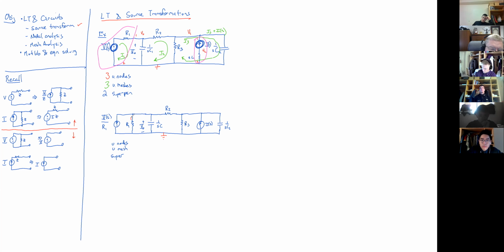Okay, so let's get above the R1. Let's get this whole wire. All right, so that's one of them, and another is above the IS. Yep, and there's another one up here. When you're talking about a node, you're talking about everything along that wire, so that wire is pretty big. That would be our V, we'll call it VO. That's what we want to find. Here's our V1. Do you have any others? No, that's it. So just 2 unknown nodes.